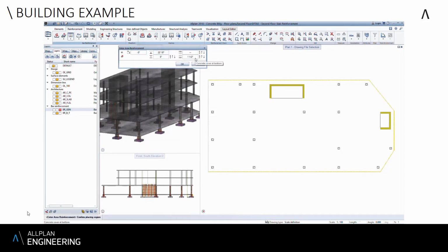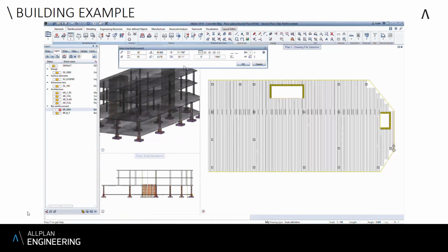So this is great if you just have a base reinforcing, let's say in the bottom of the slab. You're going to have number 5s at 12 inches on center, and you can quickly lay that out. And we can also add openings in the same way. We're just defining that there's a polygon here, it recognizes it, and it puts in an opening in the slab.